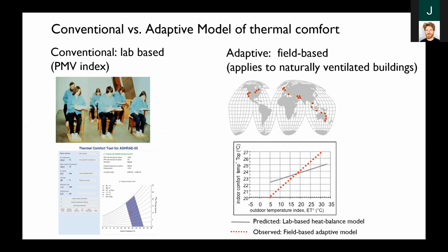comfort is objectified. Conventional versus adaptive model of thermal comfort. So it was ASHRAE RP, and you don't need to know any of these specific numbers, RP 884, that started collecting data. This was the standardization of data that was then applied across the entire database. But the conventional method that is this ASHRAE, are you feeling discomfort or not in a closed room, is being replaced at this point by a more nuanced adaptive comfort model, in which the access that people have to the environment.